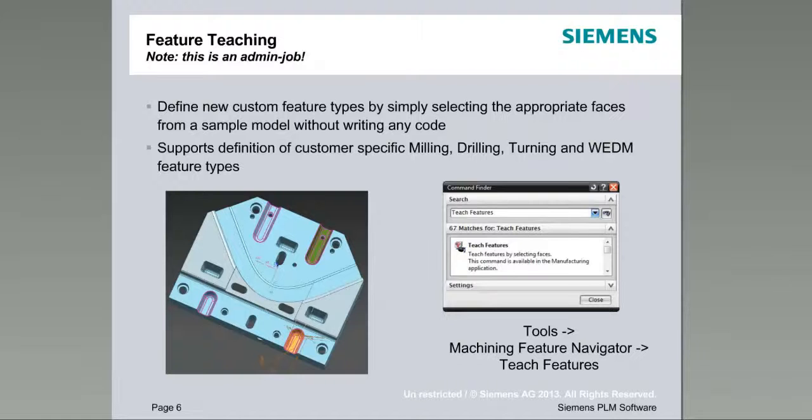Feature-based machining is extremely valuable if you can get it configured in such a way that all your users produce the same output, the same programs for similar parts. The last thing you want is to have each user teach his own operations and his own geometry. That is counterproductive. So we consider this to be an admin job, for one key user from a team. You'll see me do this live today, so it doesn't require any programming skills, but it does require some careful thinking.